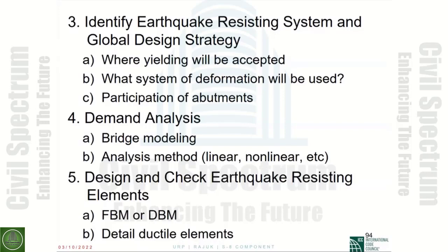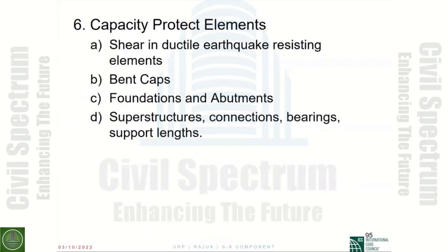And based on these things, you will do a demand analysis. You have to do bridge modeling for the analysis method, linear, nonlinear, and so forth. And then you have to design and check the earthquake resisting elements. You could use force-based or displacement-based. You will do detailed ductile element design. You have to do capacity protection: the shear, the bent caps, the shear inside the columns, the bent caps, the foundation and the footings, and the superstructure connections and the bearings.